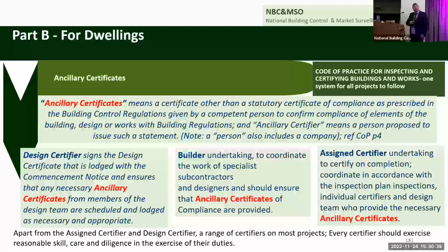The builder undertaking to coordinate the works of specialist contractors and designers should ensure that ancillary certs of compliance are provided, and then the design certifier undertakes to certify on completion, in accordance with the inspection plan, individual certifiers and design team who provide the necessary ancillary certs. So it's basically collect up all the paperwork and the design drawings with it. The ancillary design cert is no good unless you get their design with it.